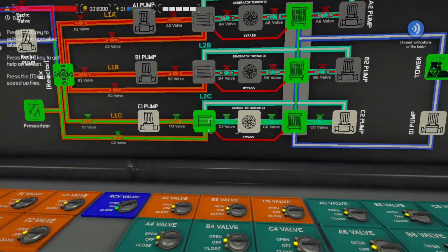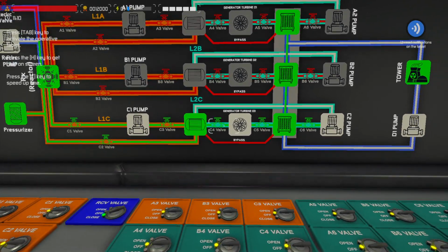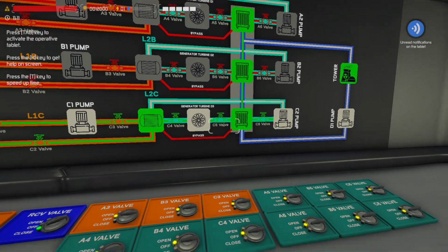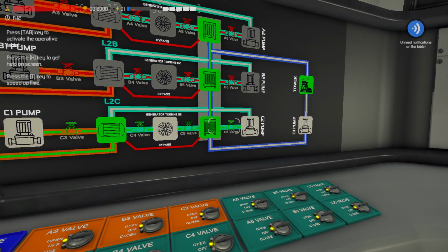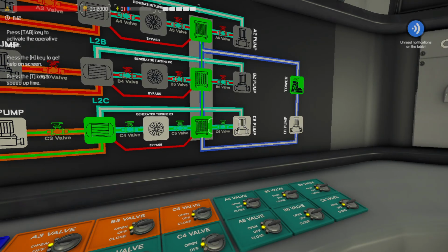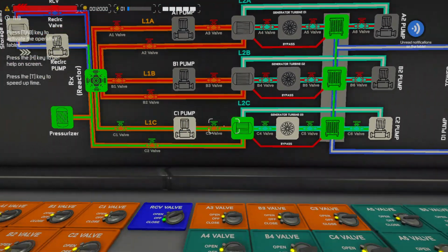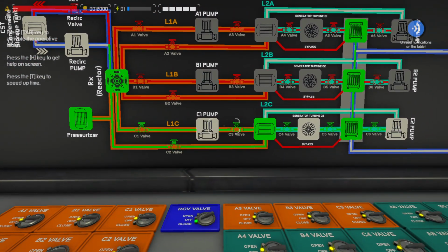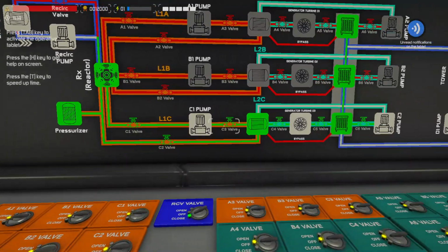So this is your steam stop valve. If you don't want to use the steam generator, you'd close this valve. This is your inlet to your condenser, and then your pump. If you have an issue with something and you need to isolate components, you can shut these valves. If you have a leak in your primary and you need to secure that loop, you're going to have to turn the pump off, and then you'll shut these 3 valves.